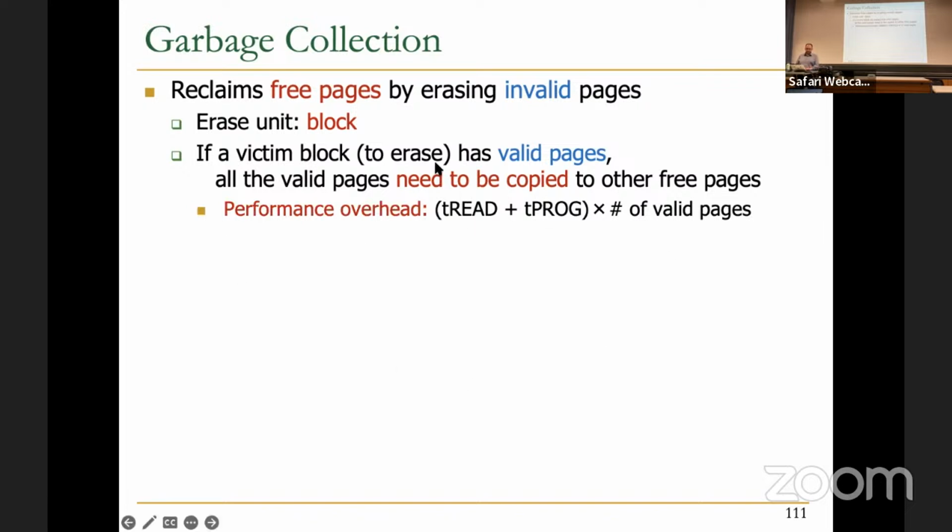So now you can see the performance overhead of garbage collection. It is dominated by the copy, not by the erase operation. Erasing is not that much. But for all the valid pages that you have, you need to read and program, because for every valid page, you need to read it and then program it.